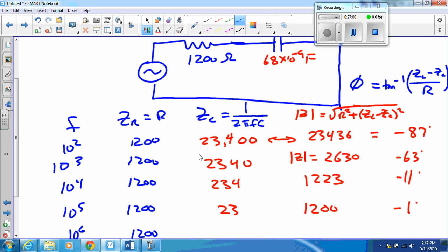We see that here in this circuit. You can't actually see the difference between the two signals, even if you shove them up. They're identical. Until, ta-da, look, there's really two. But actually, they line up. They're practically identical. Why? Because the impedance of the resistor is so large that the voltage is dropping all across the resistor. And we're getting nothing across the capacitor at all.